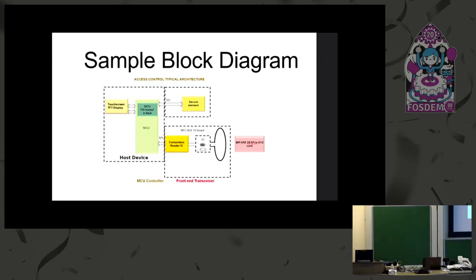So the secure element is way at the top. You can see it. If it weren't there, we would be implementing the security features on the left in the MCU. And it's certainly practical for some applications. Like I say, secure elements are not needed for everything. But if you have something requiring more security, then you could implement using a secure element and then transfer information from the MCU to the secure element over some serial protocol, like I2C, for example.